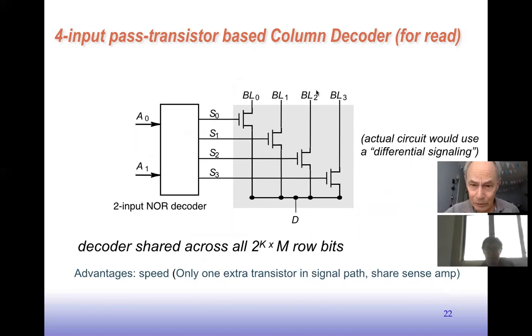Locally we have all the 0 bits, and we have a simple NOR decoder here, and we just choose to activate one of these transistors, and that will choose the proper word. In this case, the ith bit of the proper word. This structure gets repeated for as many bits as there are in a word, and they can share these select lines. So it's a way to build a distributed multiplexer.